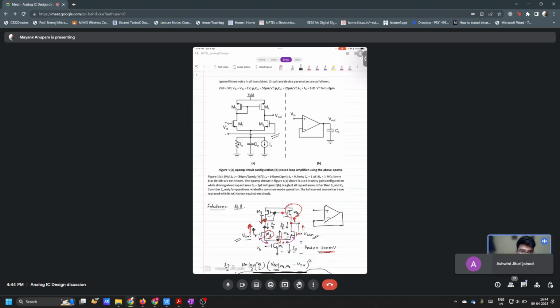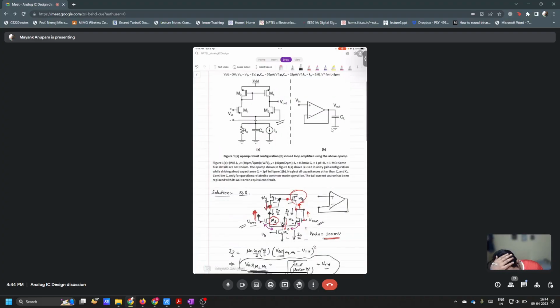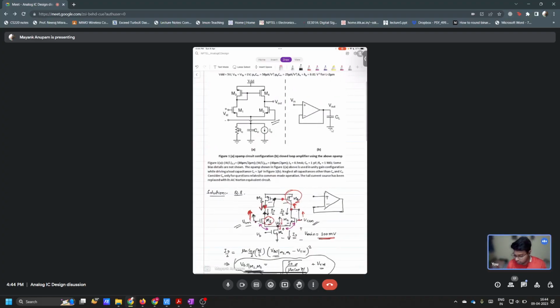And how is that negative feedback? Because the output tends to become stable after connecting it. Well, that is one way to understand it, but in general, if we apply the input, the output will become inverted. So for any system, if you want to check whether the loop is in negative feedback or not, you simply have to break the loop somewhere.